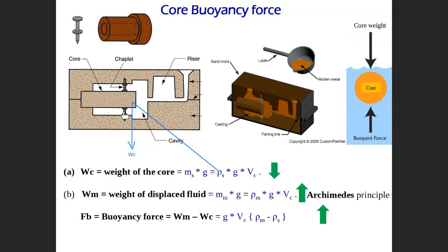When you put the liquid metal, the chaplet initially supports, later will be part of the metal, and later when it solidifies, all parts will solidify together. This extra part you can cut later by machining. Then this one will be considered as a part of the metal. It is kind of a little defect, but unavoidable. We cannot just simply remove it.